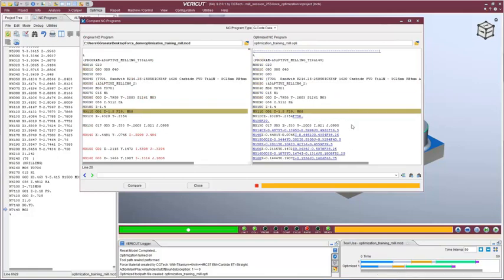Some people think that having all of this feed rate activity causes some erratic machine behavior. But in fact, what's going on is it's causing the machine spindle and the spindle load to run much more evenly than the original NC program. So the benefit to the machine is significant, as well as the benefit to the tool life, keeping that constant chip thickness right where it needs to be for machining. We have our Force users reporting from 2 to 3 times the tool life with Force optimized programs.